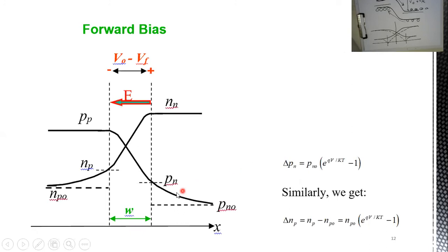And accordingly, this is the forward bias case when the minority carriers increase. As you can see, we remove the dot from here to indicate that this is not under thermodynamic equilibrium. So the carriers increase here and here, and this is due to the forward current, the current due to the majority carriers. By the way, these mathematical steps are not required from you.